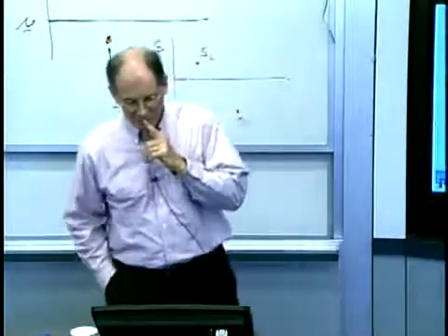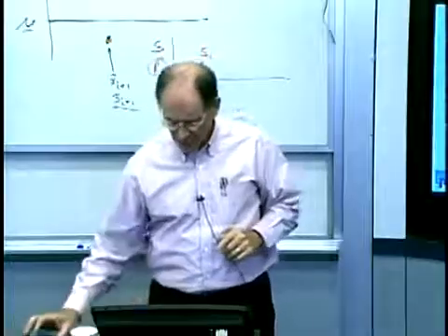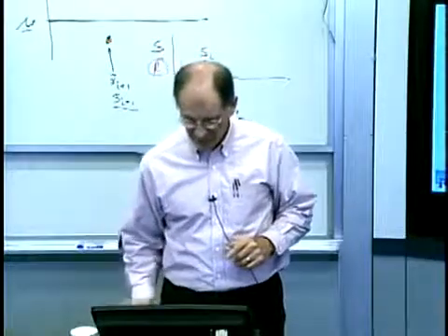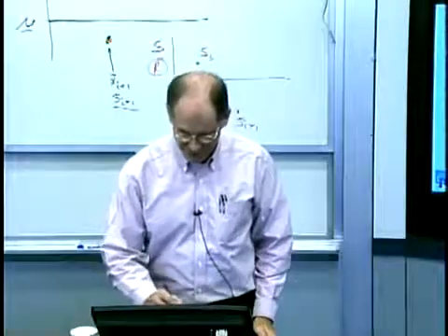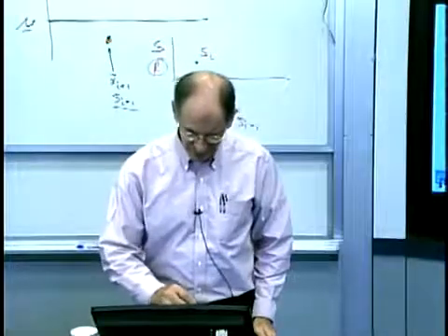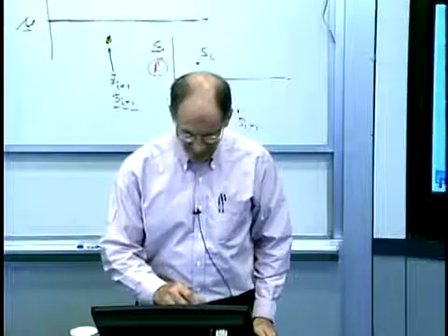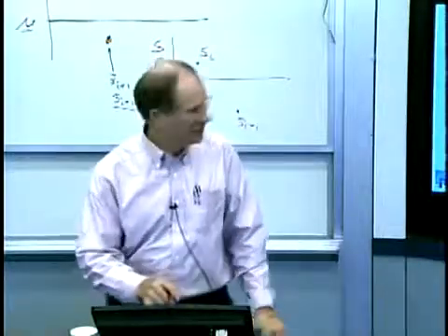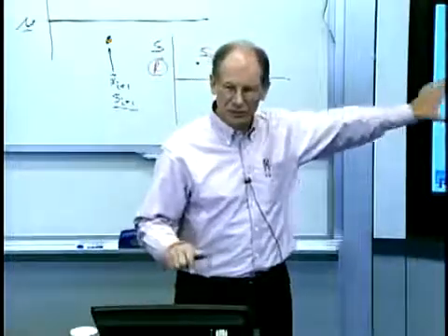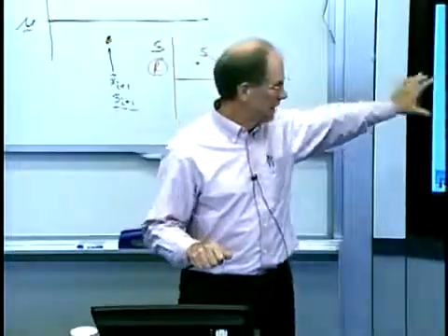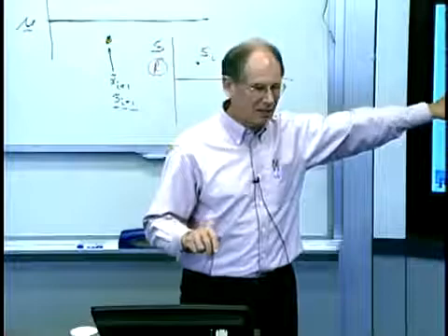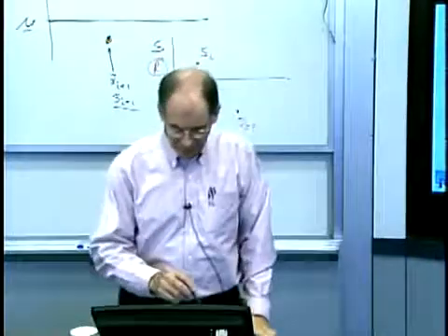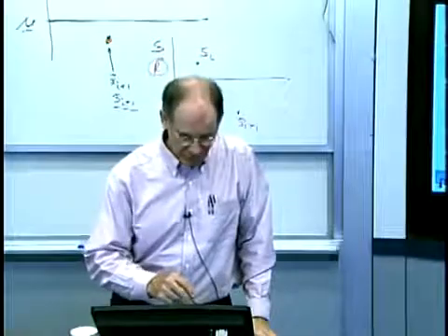But the more important thing, I think, is not waiting for that one data point that pops up here. For example, one of the reasons that might be a problem: what if I have underlying behavior that looks like this? And you can see that this is truly normal data, and it's a small enough sample set that it's highly improbable I'll get anything near the 3 sigma limit. And this is what you typically get if you had a process that was in control.